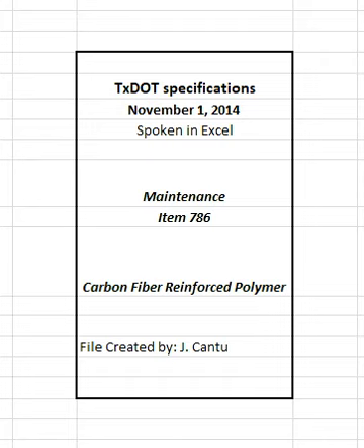Install the CFRP system 1 in accordance with contract requirements, working drawings, and the manufacturer's recommendations. Release or roll out entrapped air beneath each layer before the resin sets. Obtain approval before implementing any change to the approved installation procedure. Place CFRP anchors between layers of the applied system when shown on the plans.